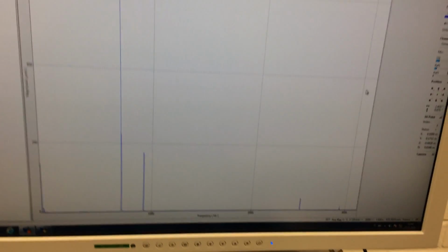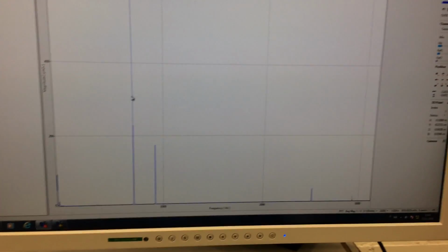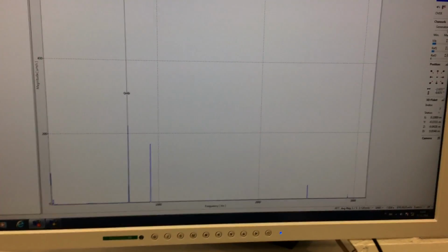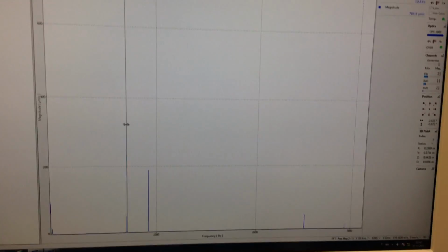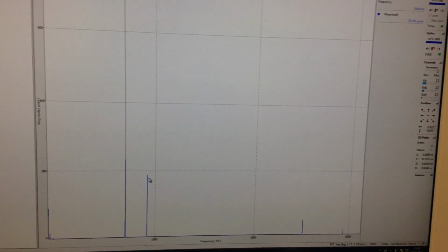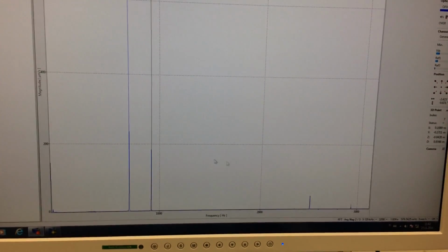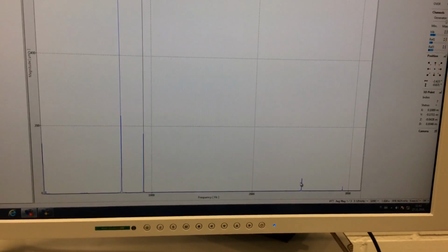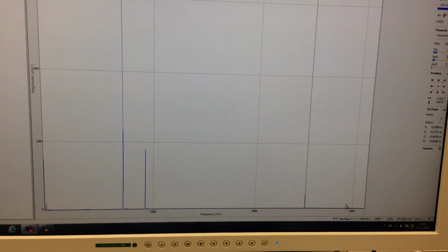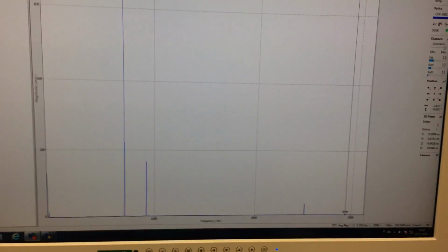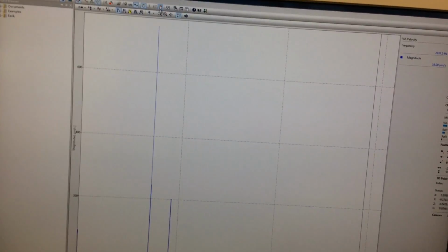Okay, this figure shows those frequencies. As you can see here, in this range, this is our first peak. The frequency is about 714. The next peak is about 900 something. At the end, about 2500, we have another frequency, and this one is about 3000. This is our fourth mode. Okay,